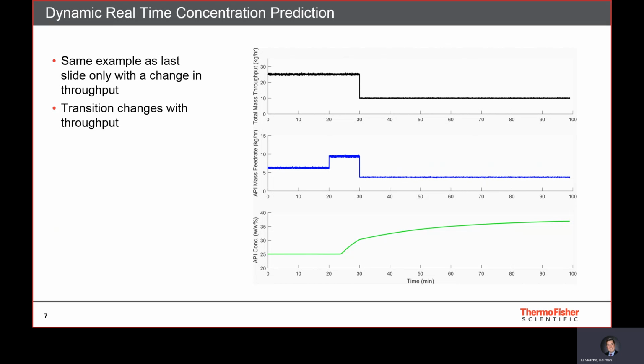As the change in throughput occurs, this changes the rate at which the mixing occurs and how the process reacts in time. In addition to changes in throughput, changes in holdup have a similar effect on concentration behavior, and these changes can be simulated with an appropriate dynamic model.